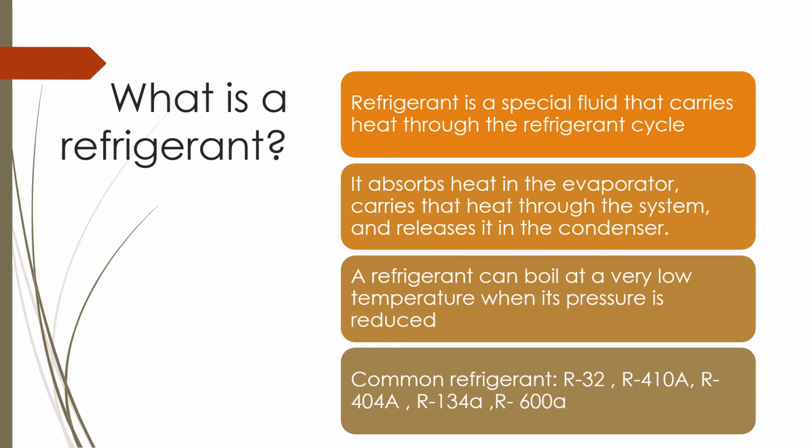First, let's learn about what is a refrigerant. Refrigerant is a special fluid that carries heat through the refrigerant cycle. It absorbs heat in the evaporator, carries that heat through the system, and releases it in the condenser. The refrigerant can boil at a very low temperature when its pressure is reduced.